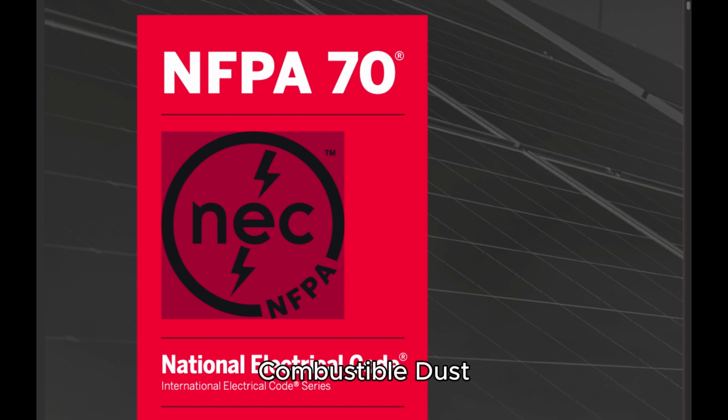CMP16 combustible dust. As applied to hazardous classified locations, dust particles that are 500 microns or smaller. Material passing a US number 35 standard sieve as defined in ASTM Standard Specification for Woven Wire Test Sieve Cloth, and present a fire or explosion hazard when dispersed and ignited in air. CMP14 informational note. See ASTM E1226-2012a,